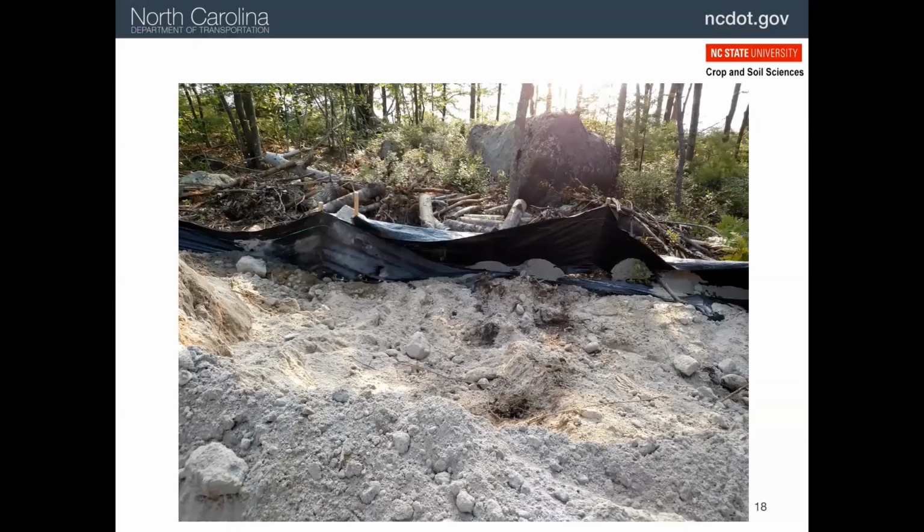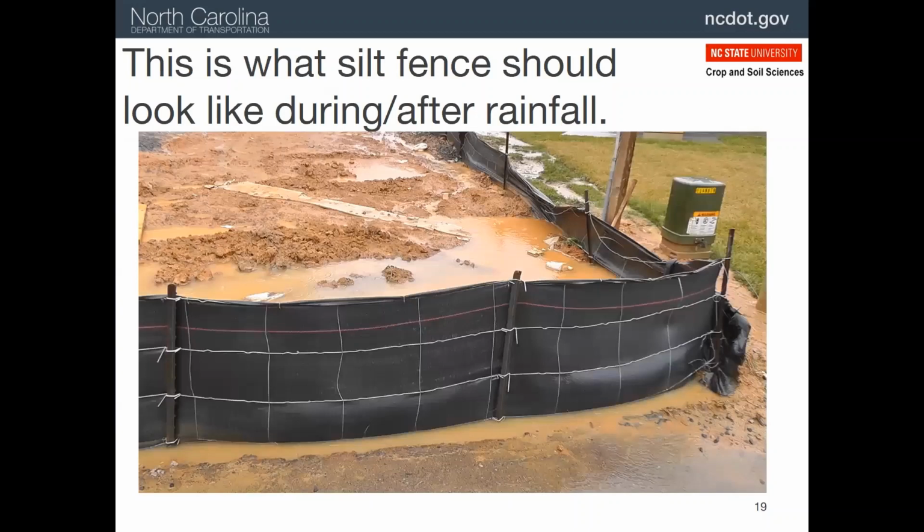There is not a single correct part of this installation of this silt fence. Remember the saying, if the bottom is flapping, it ain't trapping. A properly functioning silt fence will accumulate water behind it and slowly release it after the heavy sediment has settled out.